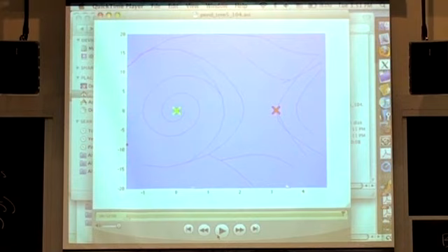Okay, so this is exactly the feedback motion planning idea that I'm most excited about right now, right? Because for the LQR controller, it depended on the thing we've worked out: if the cost-to-go function is this, or in the time varying case this, then I can come up with a very nice representation of the basin of attraction based on just a scalar value. And I could just start designing funnels through my state space, right? And the vision is, if you can think about the funnels as you build them, then you don't have to build too many trajectories to start filling the state space.